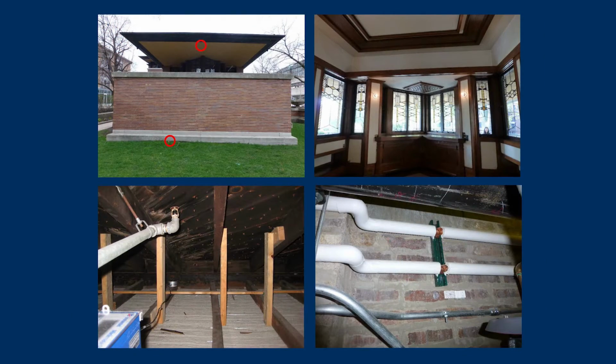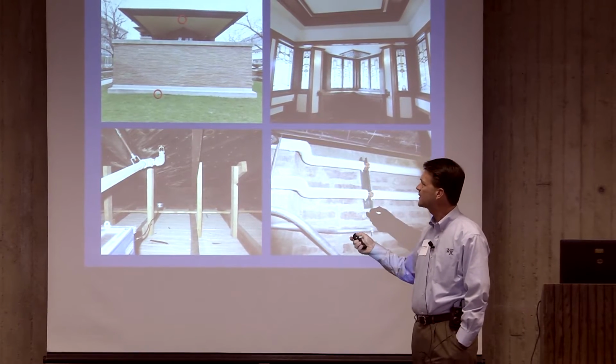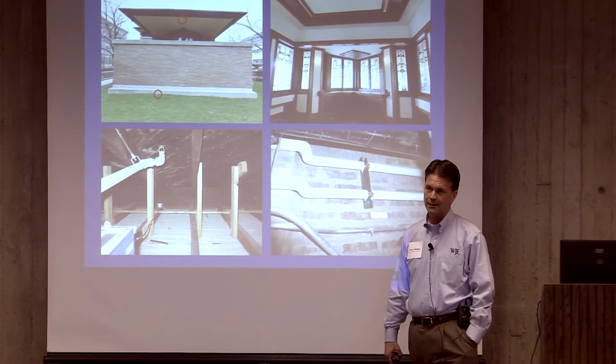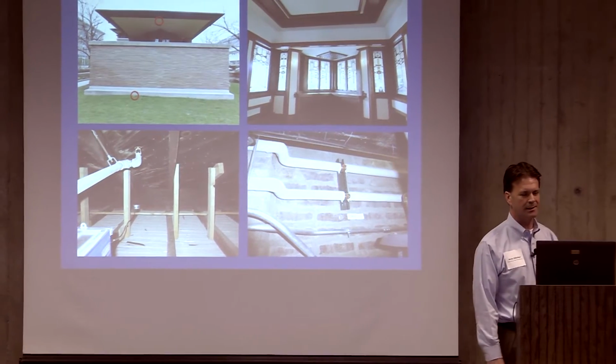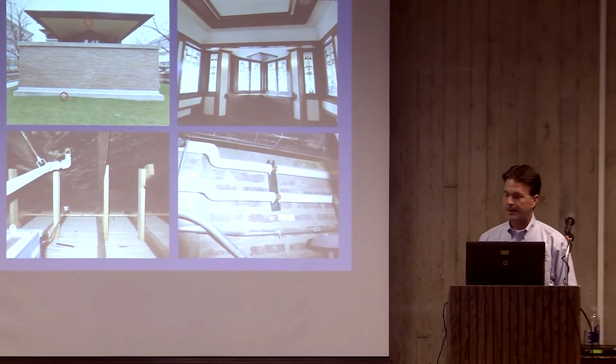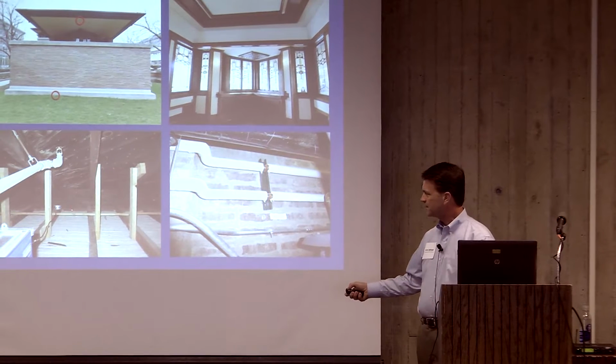We installed 2 seismographs in this building, one in the basement, not in the soil. It was actually in the basement inside the building, set to 0.2 inches per second. And then they had us put one up here in the roof cantilever because they were concerned about the cantilever maybe starting to bounce around. What we found was that the cantilever actually moves a lot more in the wind than it does due to the construction vibration. So that monitor didn't stay in there very long, and it didn't prove very important. That is kind of interesting, though.